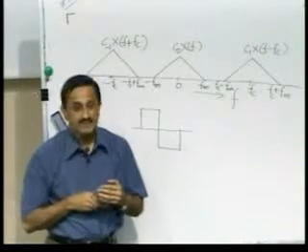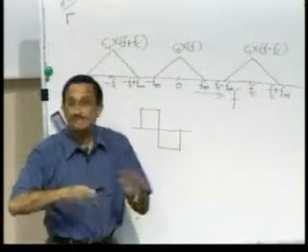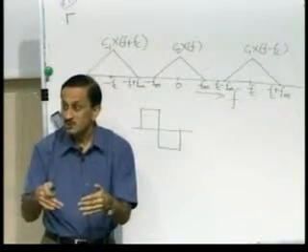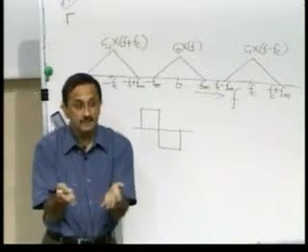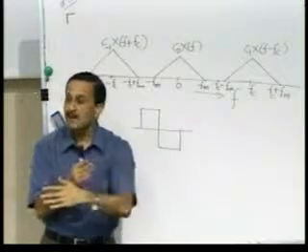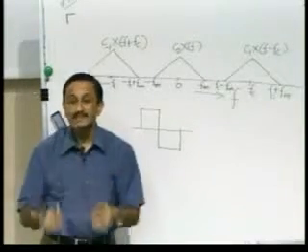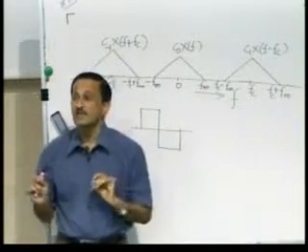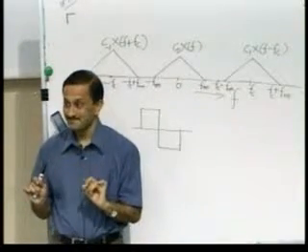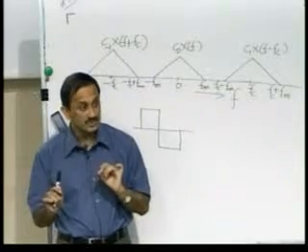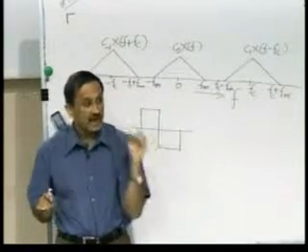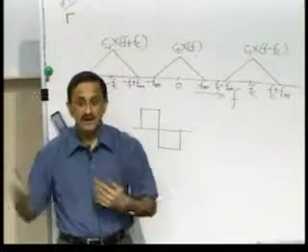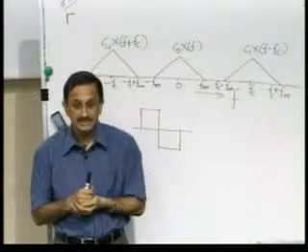So, gating pattern is something which you can construct without multiplications in hardware. You could simply construct it by allowing the waveform to pass as it is or allowing it to pass inverted. This kind of an arrangement can be made with diodes. Well, some of you may have been exposed to the idea of a full wave rectifier. What does a full wave rectifier do? It passes the sine wave as it is for half the cycle and inverts it for half the cycle. Let's say that's an example of gating.